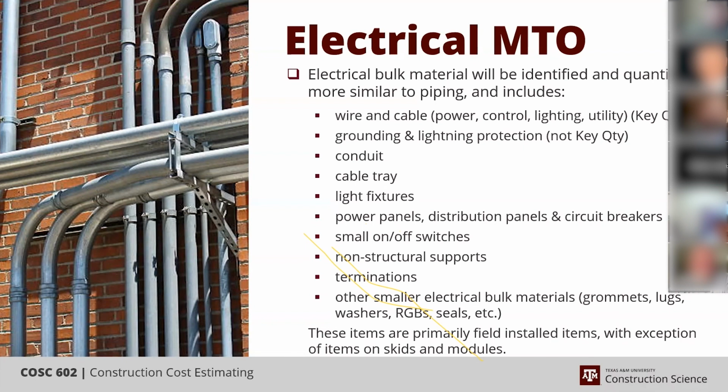And so you have to have enough lighting to support that. That's going to drive your number of fixtures, which then will drive the size of your panels and how much cabling you need for that particular area. Same with utilities, with your industrial receptacles for utility support spread around the plant itself.